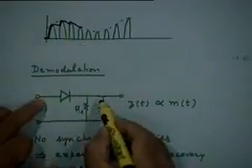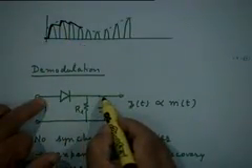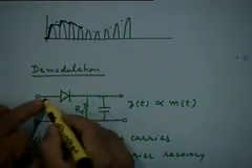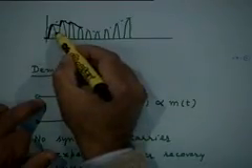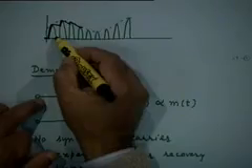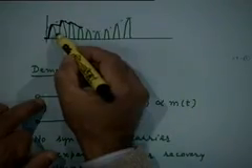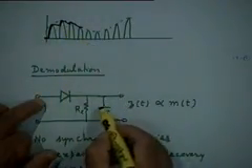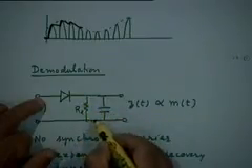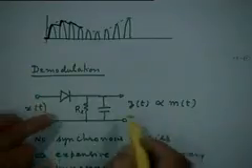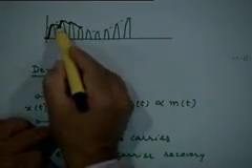And when the input voltage now drops, this diode becomes reverse biased, because this point is at a higher voltage than this point. So there is no conduction, the diode remains reverse biased during this falling portion of the carrier half cycle, and during this period the capacitor discharges through this load resistance R_L, and let's say there is a certain discharging time constant which is not too fast.